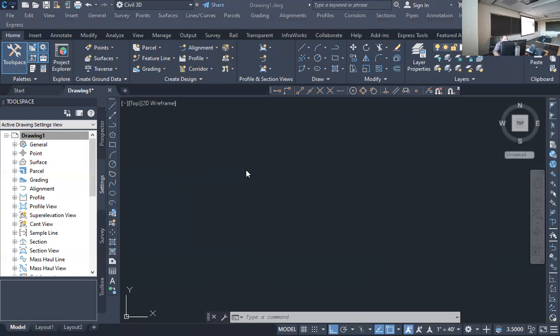there's the Colton benchmark, Centennial. So if you open up the data sheet for Centennial, okay, you have, I'm sorry. That's okay. So you have your height at NAVD 88, 348.94. Okay. But we're doing X and Y. We're doing northern and east. Just remember, CAD always sees X comma Y. Surveyors always see northern and east. So it's backwards. Okay. Just be aware of that.